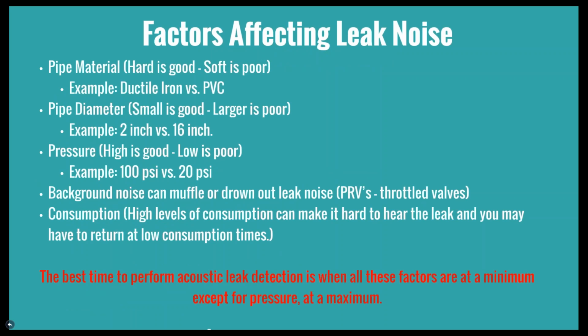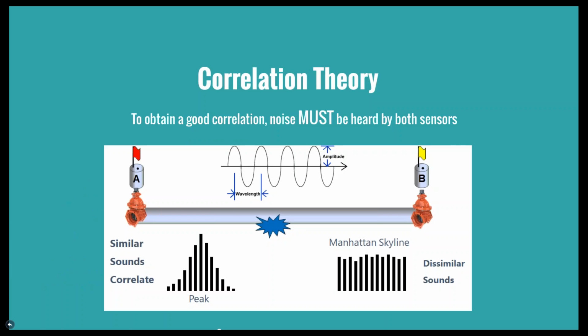So again, just a summary of the factors impacting leak noise. Keep in mind material, pipe diameter, and pressure, all things to keep in mind when you're doing a leak detection survey. Background noise, making sure that you get those minimized as much as possible. And then even the consumption. So doing surveys when services aren't being used, with loggers collecting data at low demand times of the day. Go ahead, Noah.